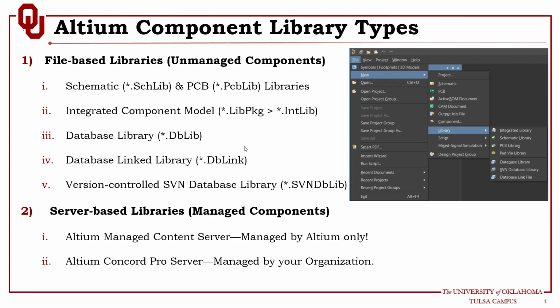So if you have 2 resistors, or 1,000 resistors, they are using the same symbol, so you don't have to create this symbol and copy it into the schematic multiple times to create a new component, unless you are using the same component and you are trying to change the information or the part number for this component in your schematic. So this is very handy when it comes to database libraries.